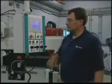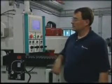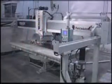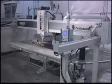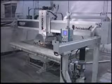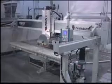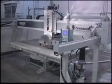By setting amp control, the saw's computer will control the cutting speed of the arbor to maximize the efficiency of cutting. By adjusting the x-axis speed to maintain a target amperage, the Yukon II can automatically compensate for variations in stone hardness and cutting depths, allowing for unattended operation.